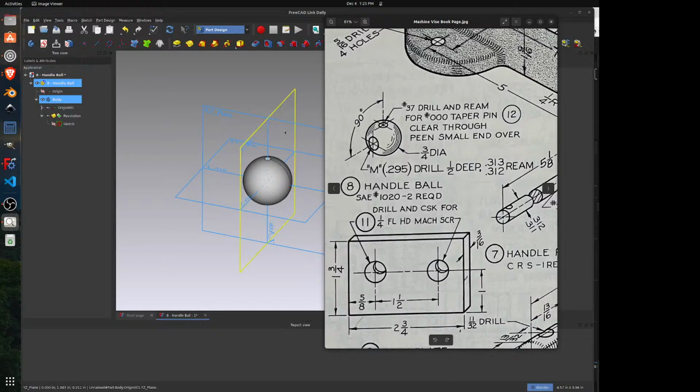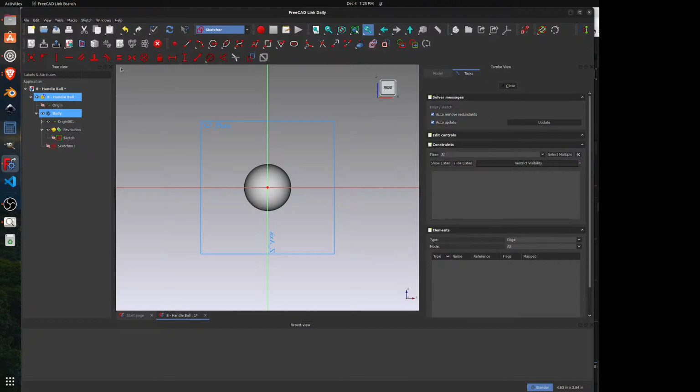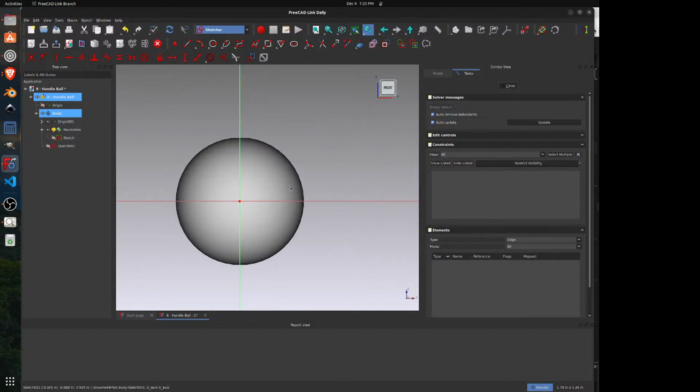and it doesn't necessarily matter the orientation here. In fact, I'm actually just going to come back in here, pick the XZ plane, create a sketch, and then I'm going to use the polyline and draw the cross section of what a drilled hole would look like. And again, we're going to revolve this around this horizontal axis, and then the diameter of that hole